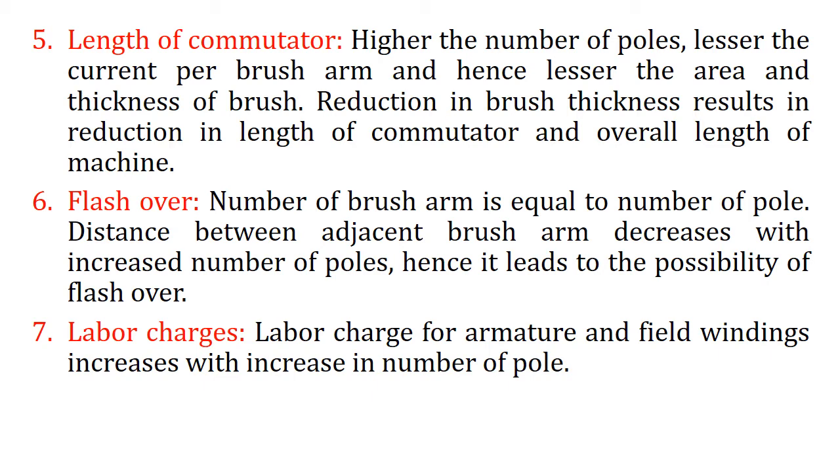Next point is length of commutator. The length of commutator is determined by the size or thickness of brush, and thickness of brush depends on the current through the brush arm.